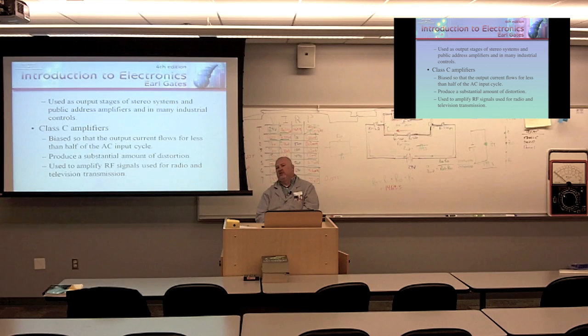So like if you listen to the conservative broadcast of KISW 99.9 FM, the Rock of Seattle, that's what we're talking about. The amplifier that amplifies that 99.9 million hertz. That is typically a Class C amplifier. So if you looked at the schematic diagram up at the transmitter, you'd say, oh, wow, okay, yeah, this looks like a Class C amplifier because it's used to amplify the radio frequency, 99.9 FM, not the audio that you listen to. Obviously, if they're broadcasting out the audio using a Class C amp, it would sound like crap. Nobody would listen to that station.